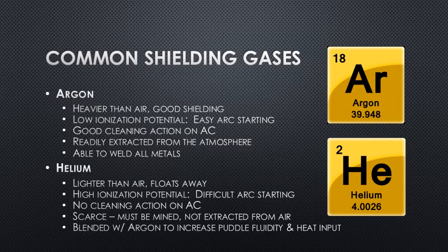Oftentimes, in order to get some of the benefits of helium, which does provide more heat input and puddle fluidity, we would blend that with argon to achieve the benefits of both worlds.